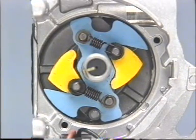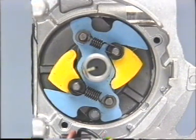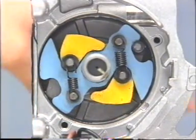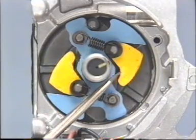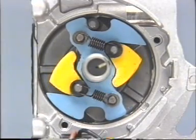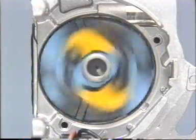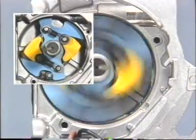The governor advancer consists of a cam plate, flyweights, and governor springs. The cam plate rotates together with the distributor shaft. Two flyweights rotate on the cam plate with support pins as their centers. At low engine speeds, the flyweights are kept closed by the force of the springs.